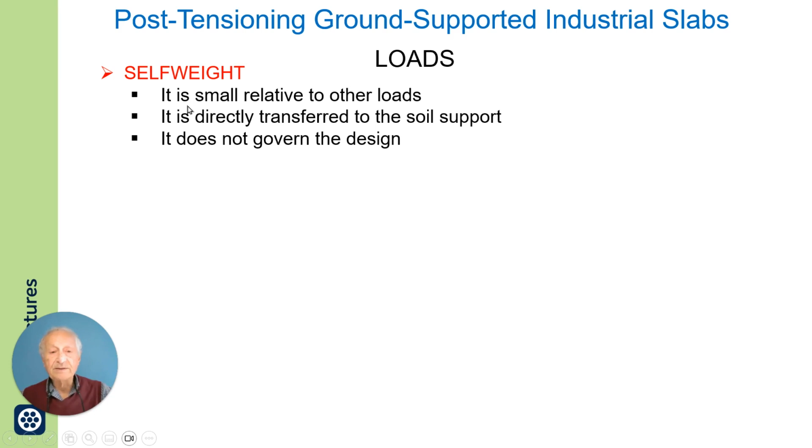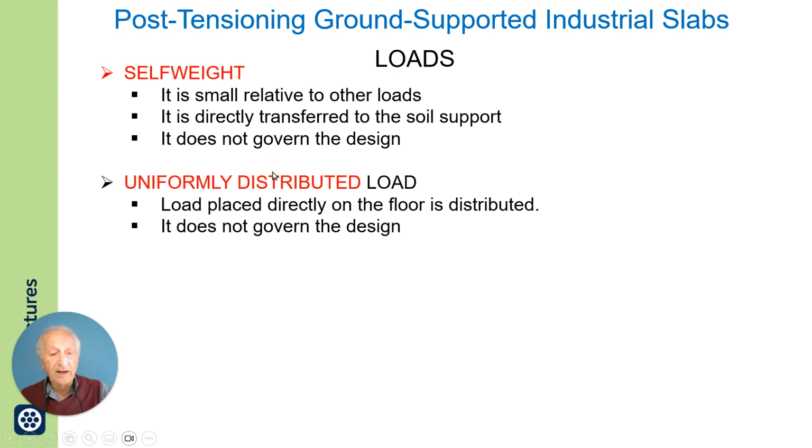Now, what about the loads? Self-weight obviously is small relative to other loads. It's directly transferred to the soil, does not play a significant role in design. It doesn't govern the design.